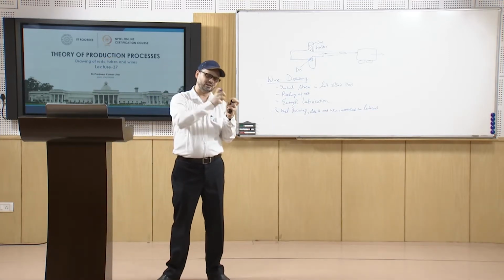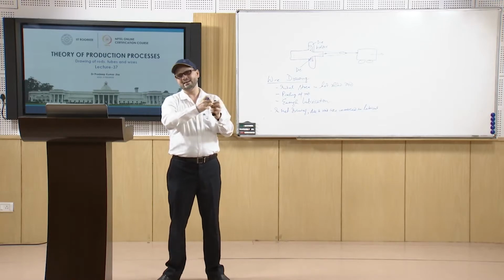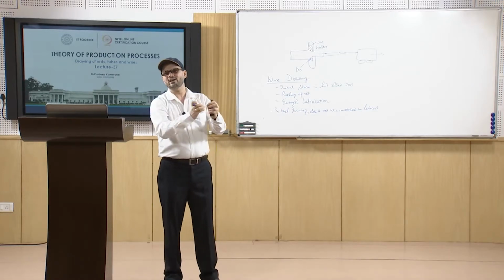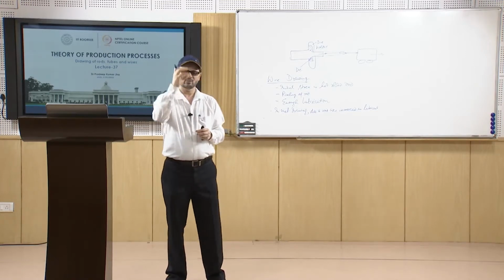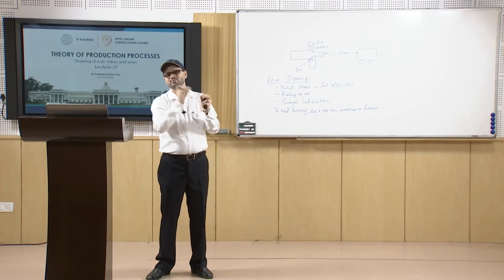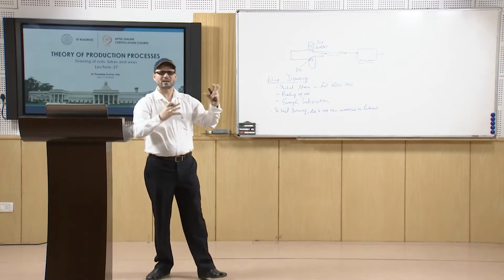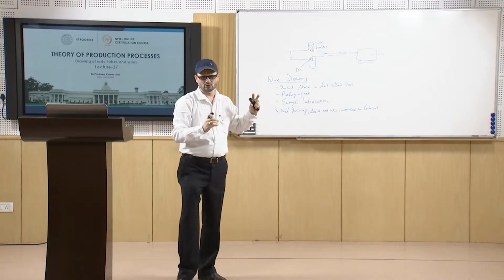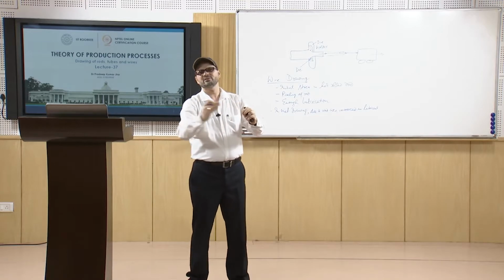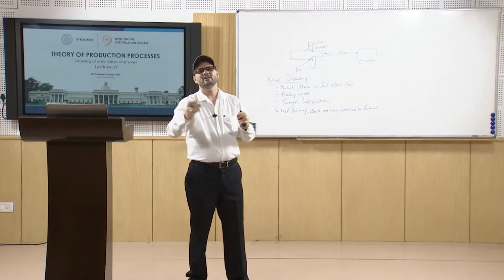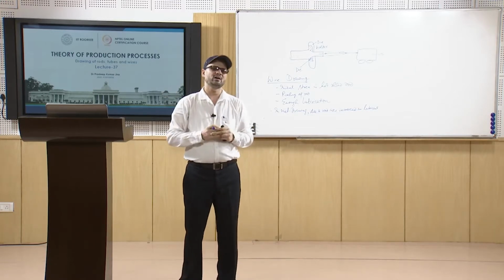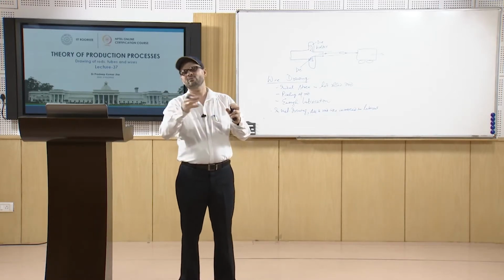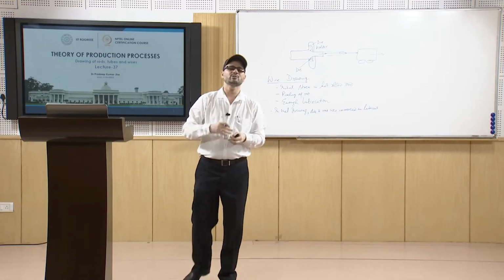So, from one place it will go to another. It will enter into another die setup, and then from there it will move to the next one. Every time it goes into the first die, it will come out with a certain reduction, then it will move to the second die machine, and there it will result in a further reduction.